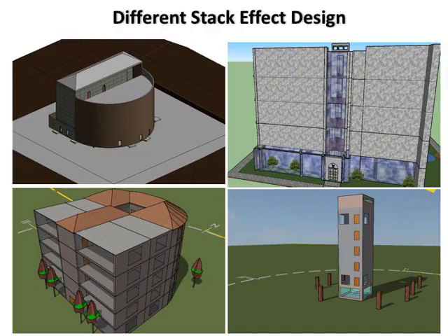The model was designed in IESVE, and the analysis covered only the lounge at the ground as well as the fourth floor, since it has many windows and is connected directly to the lift, which also acts as a shaft in the study, in order to study the effect of the stack.